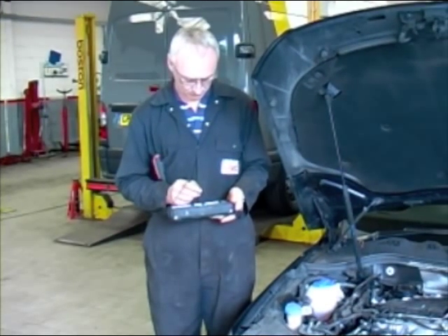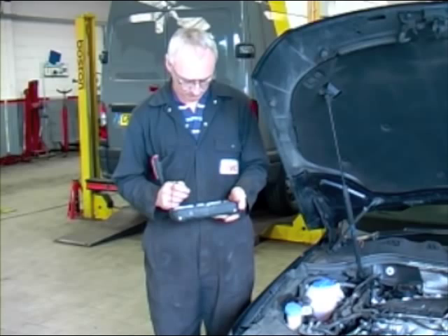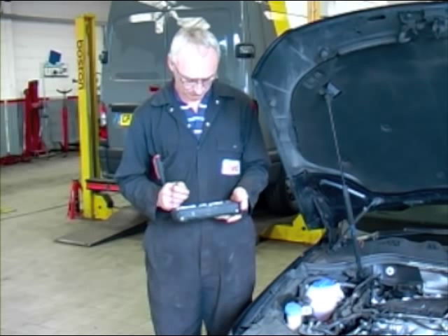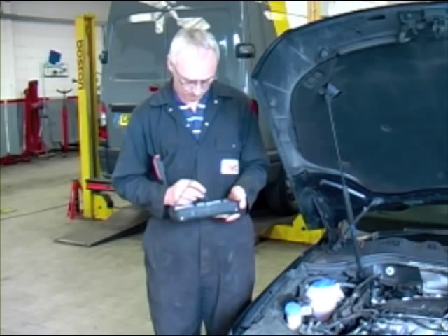The technician has connected the diagnostic tool to the vehicle and is scanning for OBD error codes. The OBD, or onboard diagnostic system, is there to detect, record and display error codes which occur in emission control relevant components. The intention is to prevent severe damage to the engine components and reduce the car's negative impact on the environment.